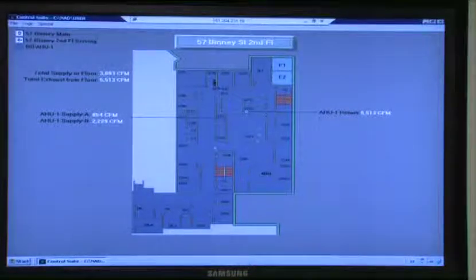But no exhaust, huh? 0 exhaust on the 2nd floor? Exhaust fan? Yeah, there's no exhaust on the 2nd floor? I'm sure that there's meant to be a flow station that's missed. I think there's one, like exhaust fan 14, that didn't get dropped on here. Okay. So just put that as a note, that 2nd floor exhaust.